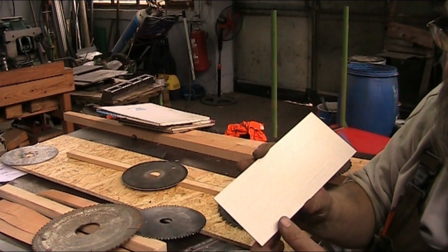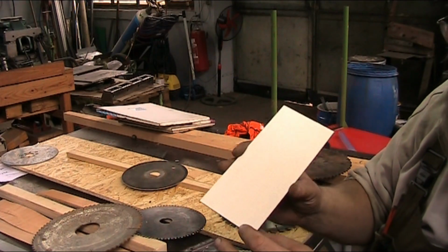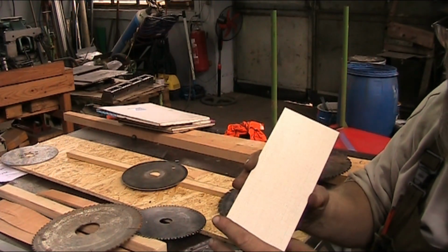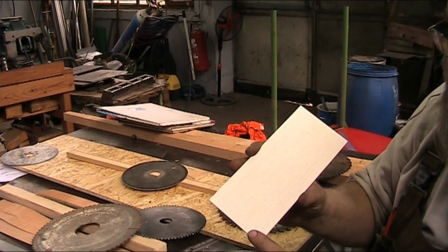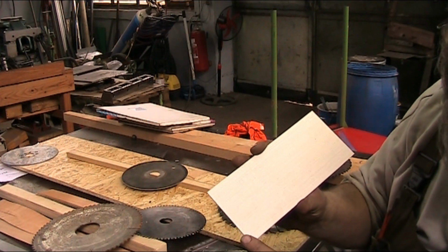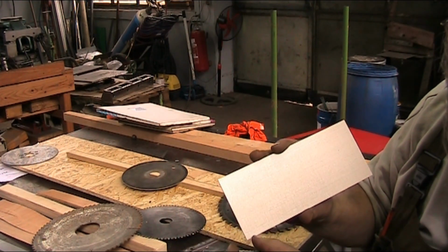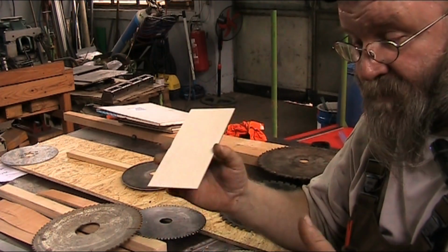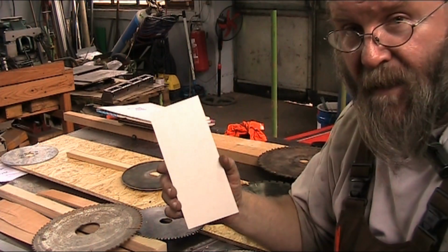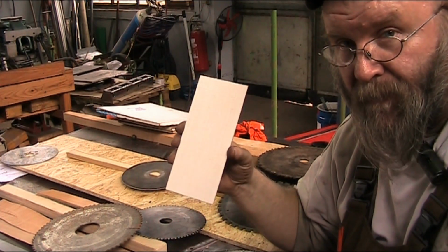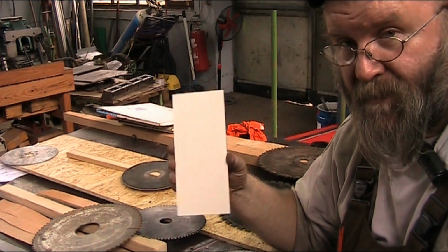The other thing you can do is sandwich this stuff where you have two pieces of melamine facing each other in a mirror fashion, and then you put a double-sided tape over the area that you're going to cut, and that way as the blade passes through. Now this is just for folks who don't have the money to pick up a negative rake saw blade to cut this kind of stuff.